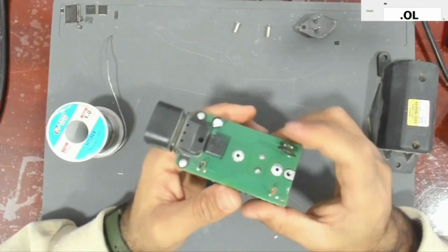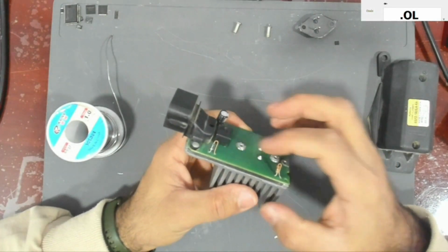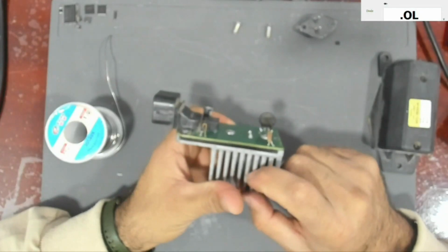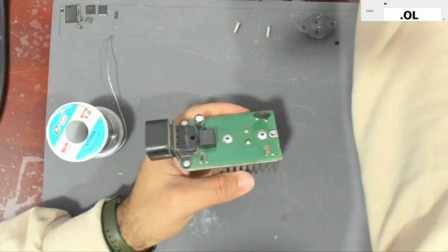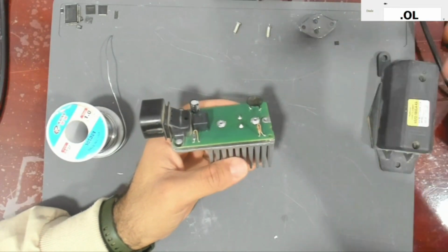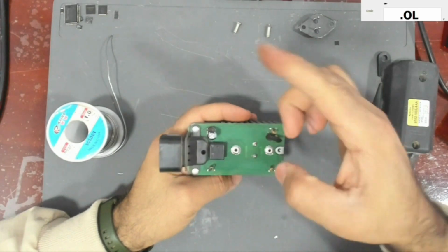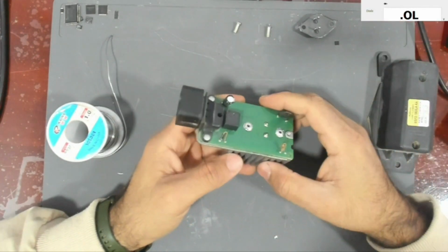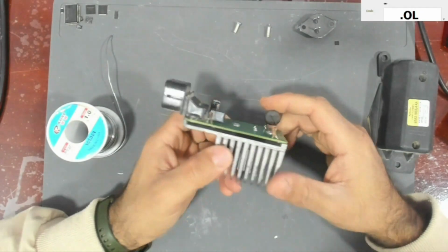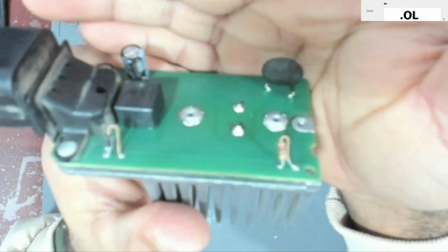We have soldered these two. They took a lot of time because these are now connected with this heatsink, and this heatsink absorbs all the heat that I am putting from this soldering iron. So I used a hot air station to aid this soldering iron, and now it's okay, I think. If you can see.